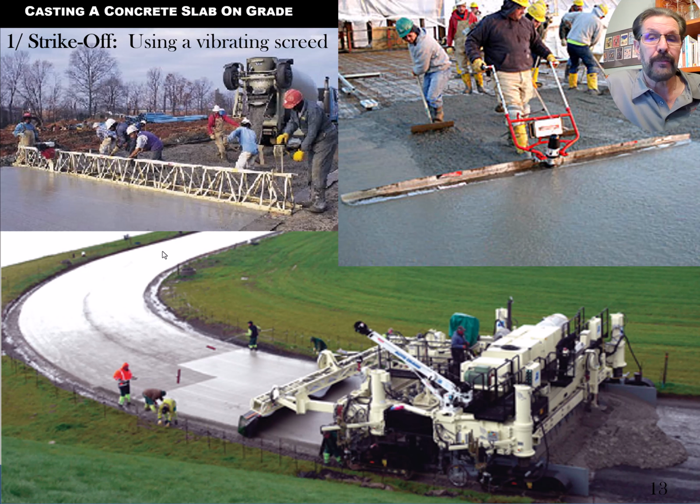Here's another kind of strike-off process with screeds. Anything that's striking off the surface is called a screed, so these are all considered screeds in all 3 of these pictures. You've got a vibrator mounted to a straight edge here up at the upper right-hand corner. Over at the upper left-hand corner, you've got a vibrating screed where it's a whole superstructure running across the whole lane or roadway or whatever it is. And these things can oftentimes be contorted so that they can have a curve to them. If you're going around a corner, they might bank it some way. And then this bottom picture is a much more elaborate piece of equipment that is a screed and a floater all at the same time. So it's doing the floating.